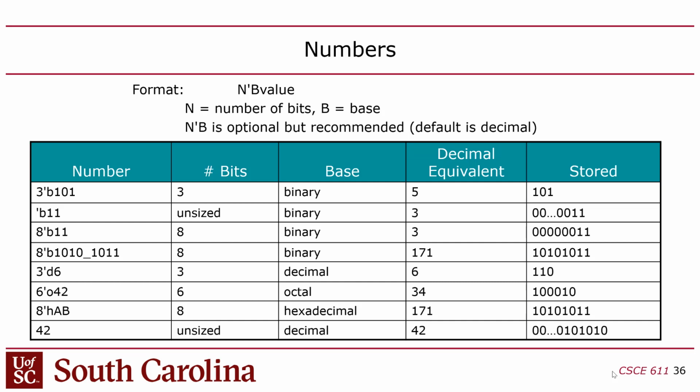So if you assign it to a 4-bit variable, it's going to take the least significant 4 bits and put it into that. It'll infer that you only want the rightmost bits, right? But it's still better to always specify your bit width whenever you have a constant. That makes sense? Okay.